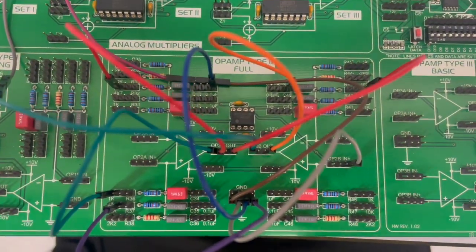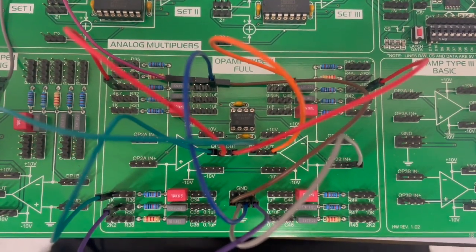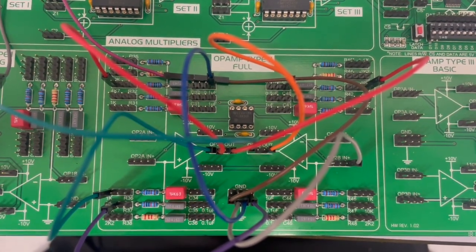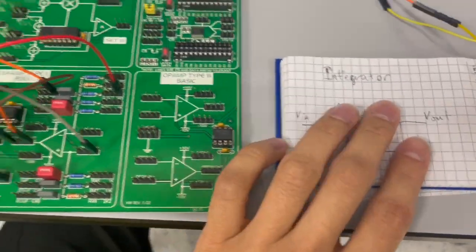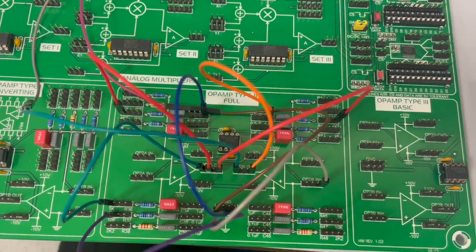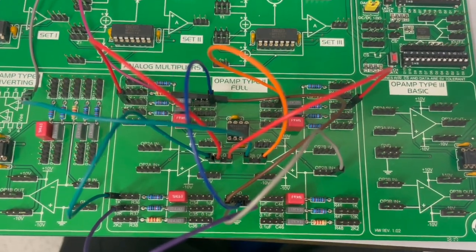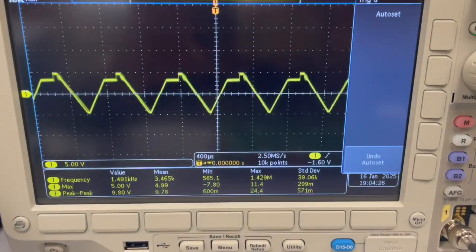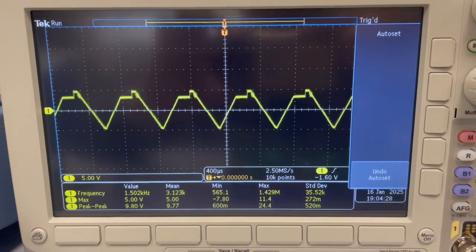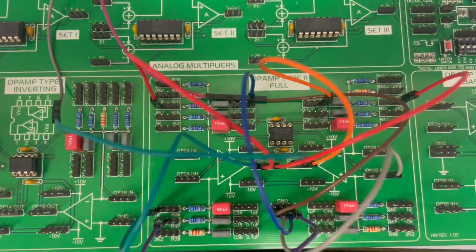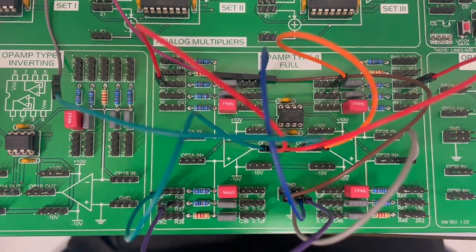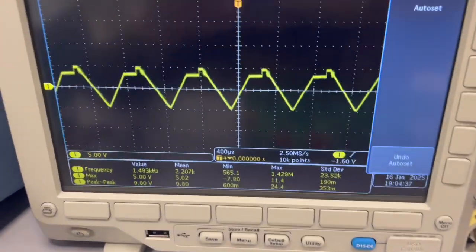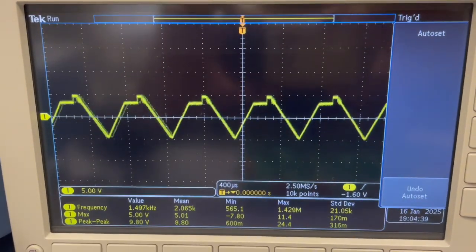So now that's it. Try to repeat the same circuit and try to generate first the square waveform by making the Astable multivibrator, and then by attaching the integrator generate the triangle wave. That's it. Repeat and try to choose different resistors and see how the frequency changes. So the task for this swap is to see how you can change the frequency of this triangle wave.